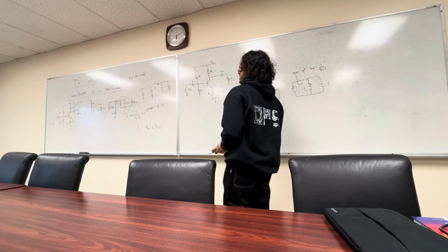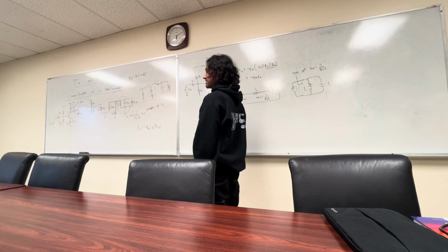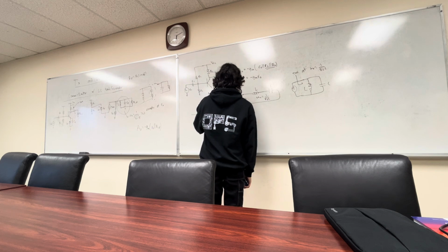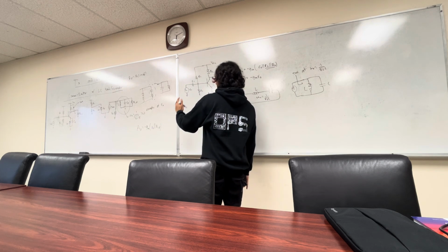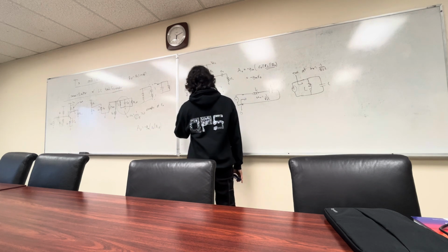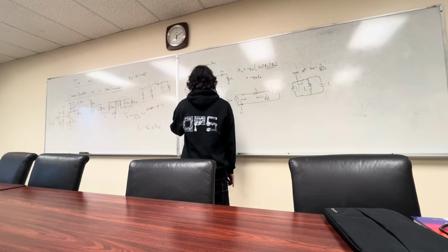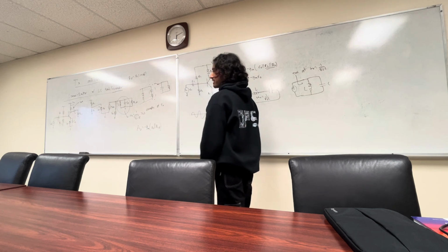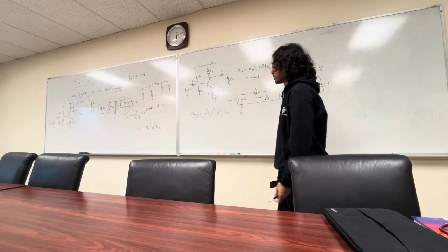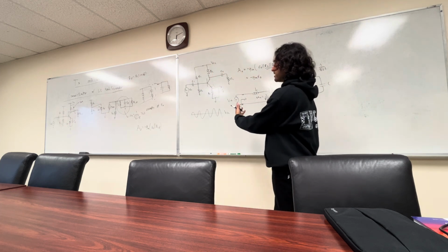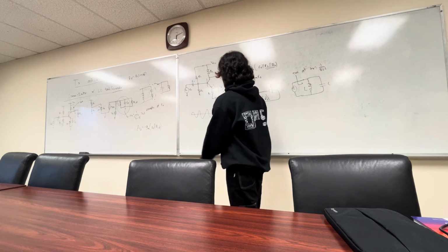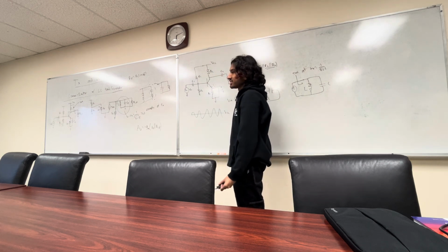Alright, so our biasing is inherently taken care of. You may wonder now, our collector's DC point is VCC. If we have a signal that gets amplified, we're going to go above and below VCC, right? Doesn't that feel kind of weird to go above VCC? Going below is fine, we've always been below, but going above feels weird. This is allowed to a certain extent. Obviously, if it's way too large, you're going to break the transistor.